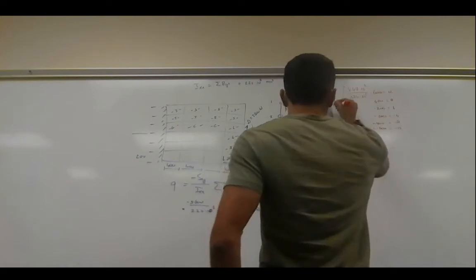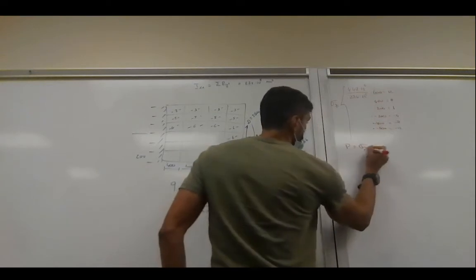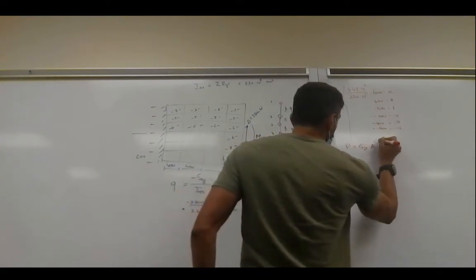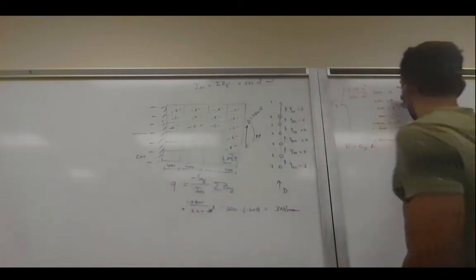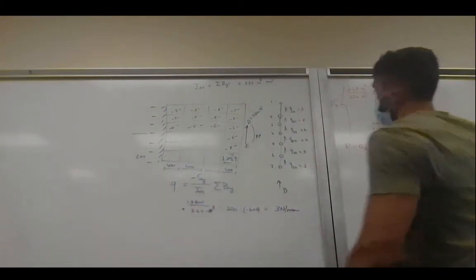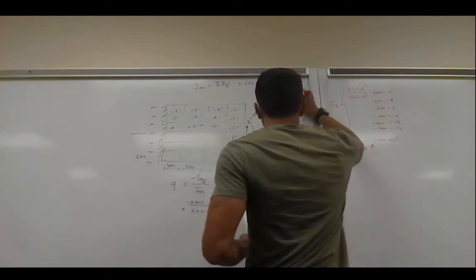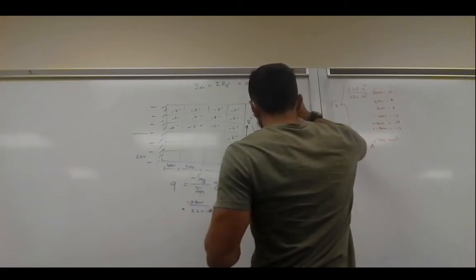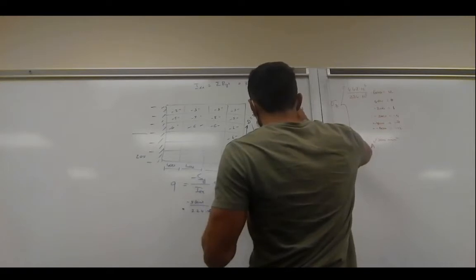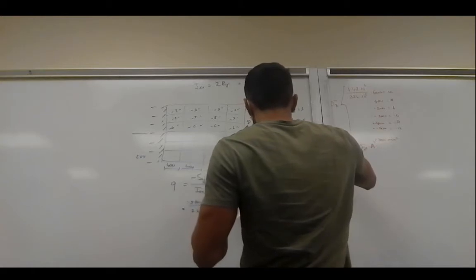So now we have the stresses. And like we said, the force is nothing else than the stress times the area. The area is given, that was 200 millimeter squared. So you basically multiply this by 200. So you get here the stresses, this becomes, so if you calculate this, the forces, this will become 2,400 Newton. This will be, of course, 1,600 Newton, and this is 800 Newton. And then we get negative 800, negative 16.